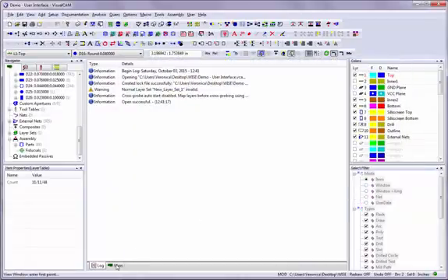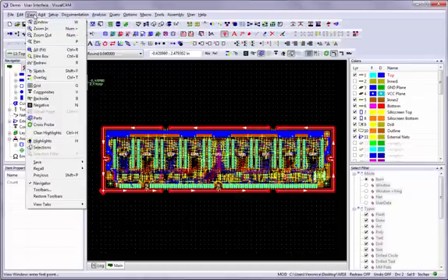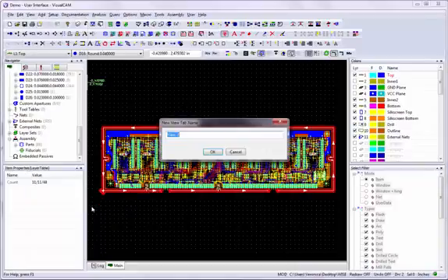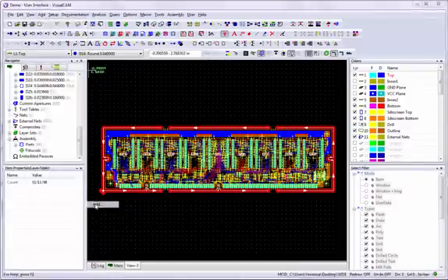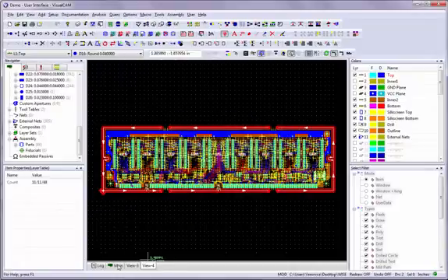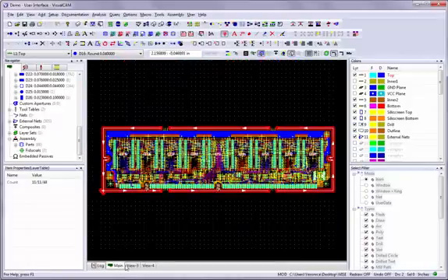The Main tab is your main working area and where you see the graphical display of your database. You can add additional tabs, maintaining one view of your database in each, so that you are not required to frequently zoom and pan your view. To add tabs, use the View tabs Add command. Change the name or leave it set to the system default. You can perform edits, such as copy data from one view to another. To delete tabs which you have added, use the View tabs Delete command.